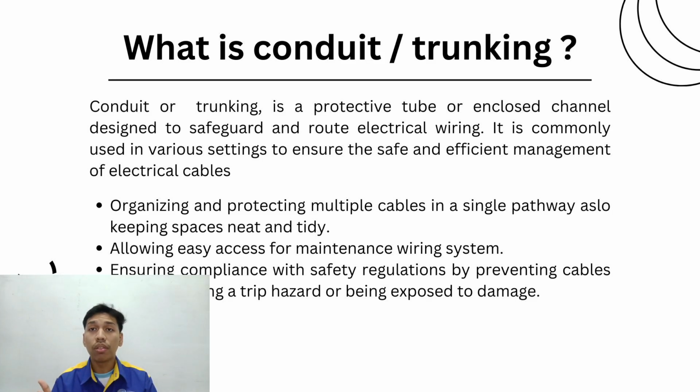So why is it important to have conduit or trunking in our cable design? It makes cables organized and protects multiple cables in a single pass, also keeping the space looking neat and tidy. Besides, it also allows easy access for maintaining the wiring system.